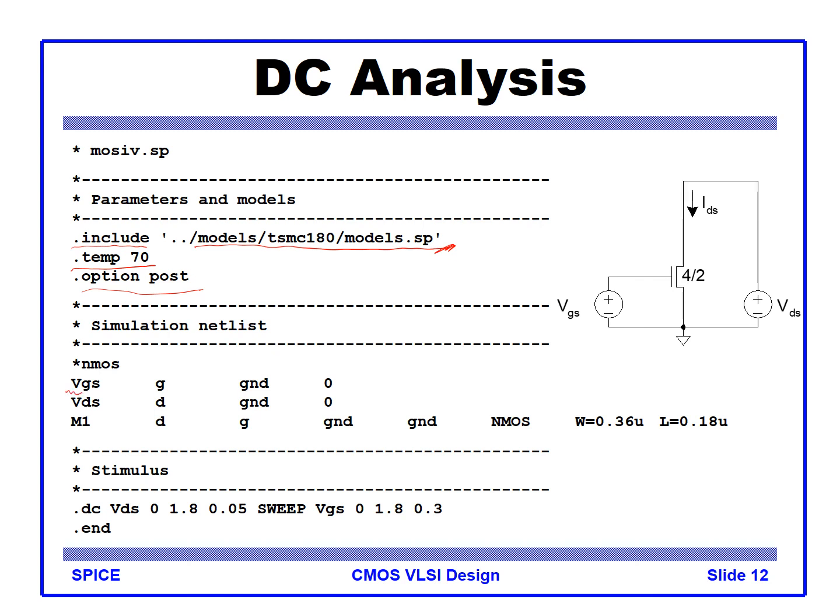So it starts with the VGS. Starting with V means this is the instance name for a voltage source, right? So VGS is between the G node and ground. We apply 0 volt. Another voltage source, the VDS, between the drain, D node, and ground is 0. So according to the schematic, this is the gate voltage G, and the drain is the D node. So there's an M1 device. If it starts with M, that means transistor.